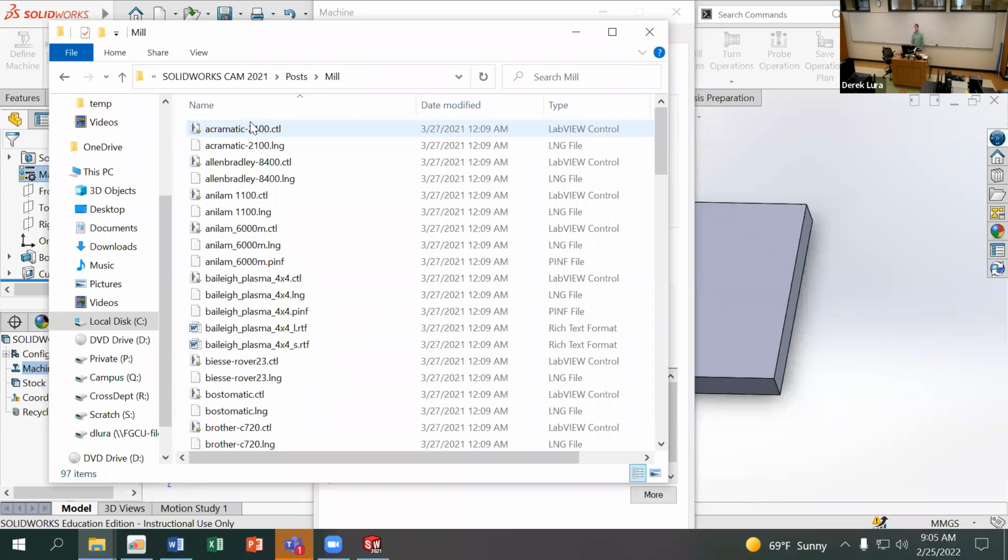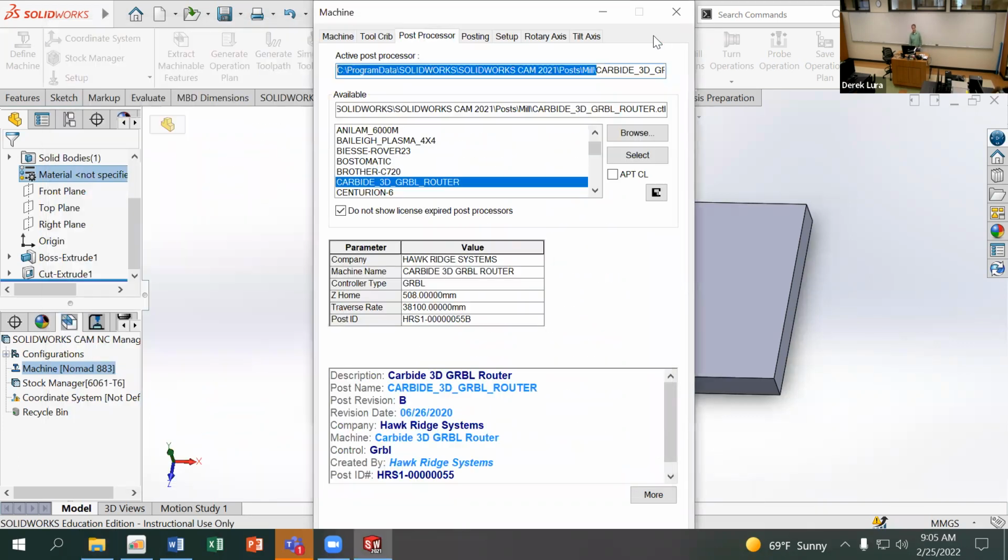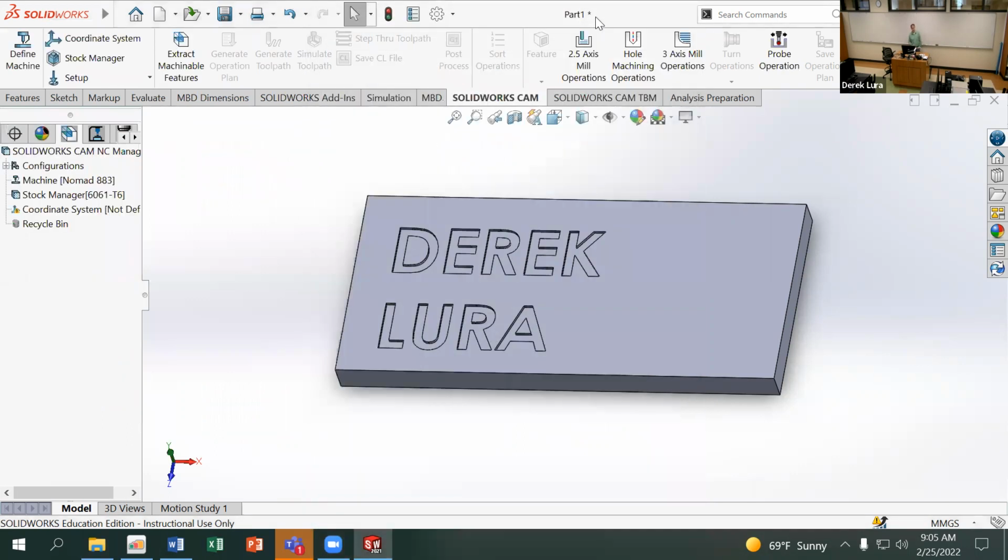All right, now we've got our machine set up. Luckily, most of the work after we have the machine set up is done by SolidWorks for us, right? So it's kind of like on the Cura side, once you've got all the settings for your slicer configured the way you want them, the process is fairly automated. I'm going to caveat that: you can't trust the output of SolidWorks through all these automated steps to actually give you what you want, because it's going to try and figure out, hey, I have all these tools, which tool and which operation is best going to give me this geometry, that one, right? And a lot of times that one doesn't work, right?